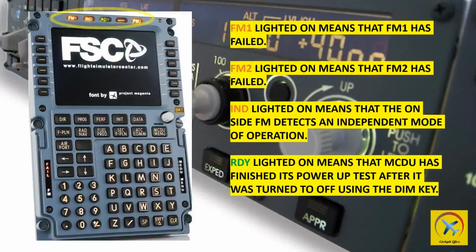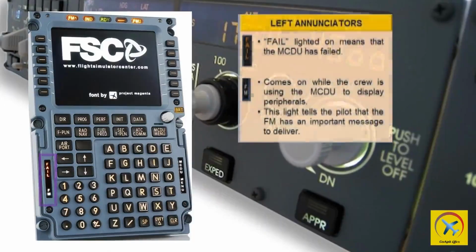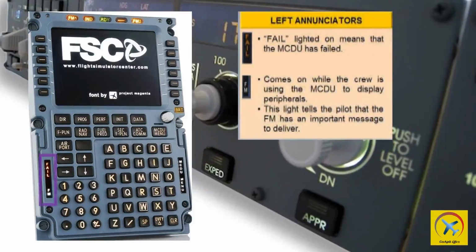Secondary flight plan allows the creation, initialization, and modification of a secondary flight plan. Airport allows the crew, on flight plan page A, to switch between the destination airport, alternate airport, and origin airport. The FAIL amber annunciator illuminates when the MCDU has failed. The FM white annunciator illuminates when the FMGC is not the active system and it has been sent a message. Use the MCDU menu key to return to the FMGC page.